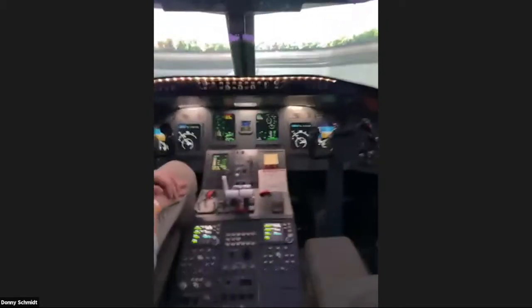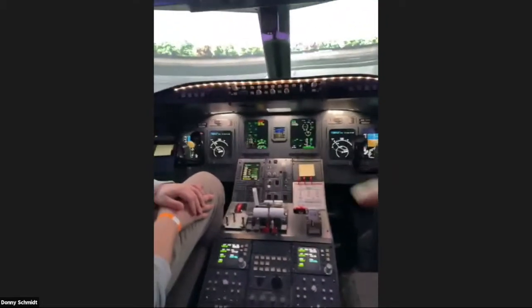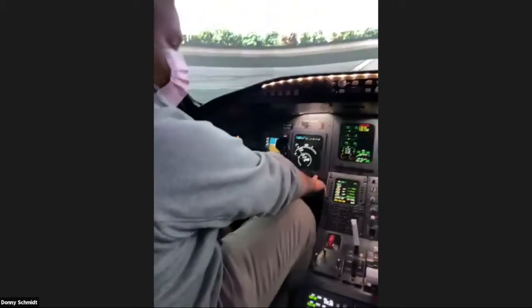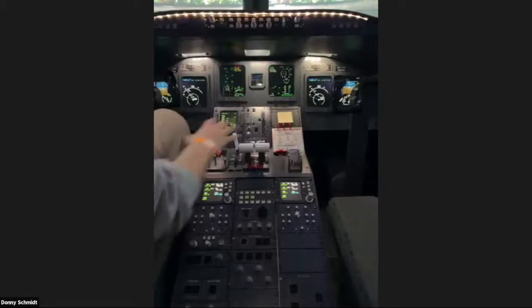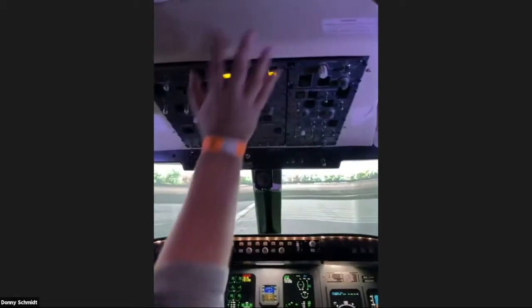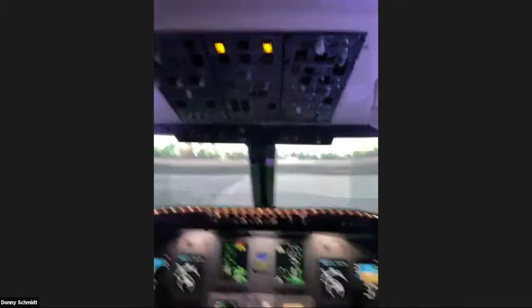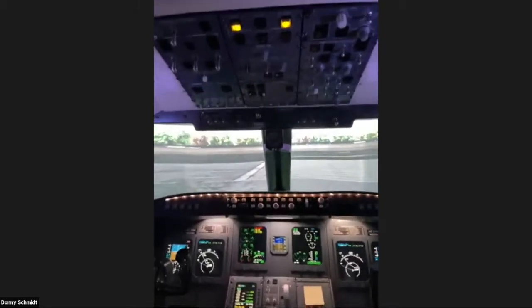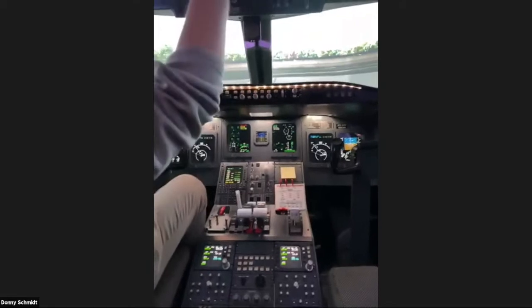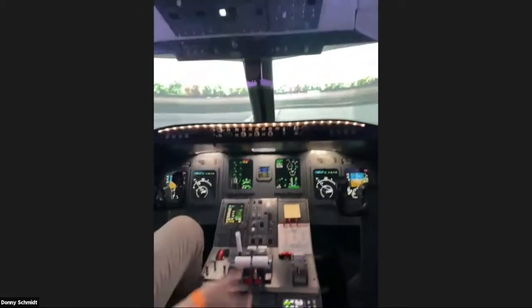So what you can see here, we've got a few different screens. We've got primary flight displays, engine instrument displays in the middle for the engine instruments, a primary multifunction flight display on Jason's side, and then obviously also on the co-pilot side. Here in the center stack, we've got things like throttles, radios, and nav radios, essentially all the switches to get the airplane running. And then up above in the overhead panel, we've got fuel information, bleed air information, air conditioning, that sort of stuff. So Jason's going to get it going. You can maybe see some lights and stuff turn on, just getting the engine started.